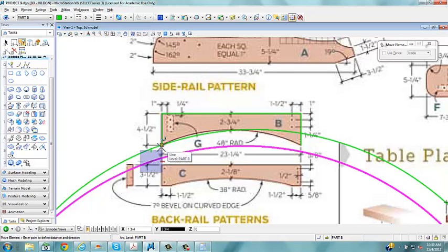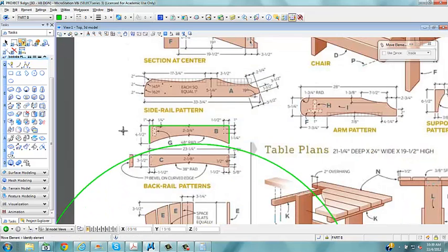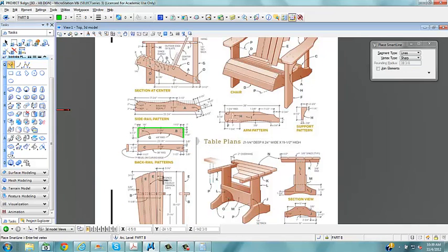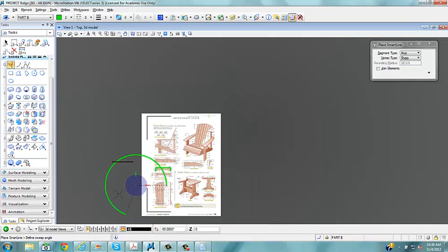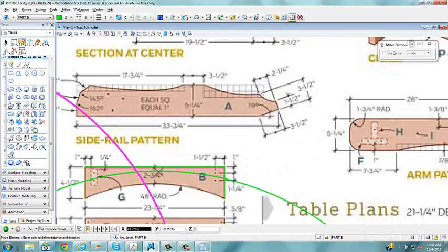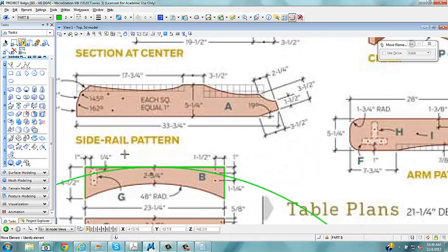I'm thinking that 48 is, pardon me while I redo this again, I screwed it up. I'm going to go tilde 48, make sure it's 180 degrees so it has a snap point right on the top, and I'm just going to let this snap to the top. So now, the reason I did that is to make sure it's centered. We're going to bring it straight down.